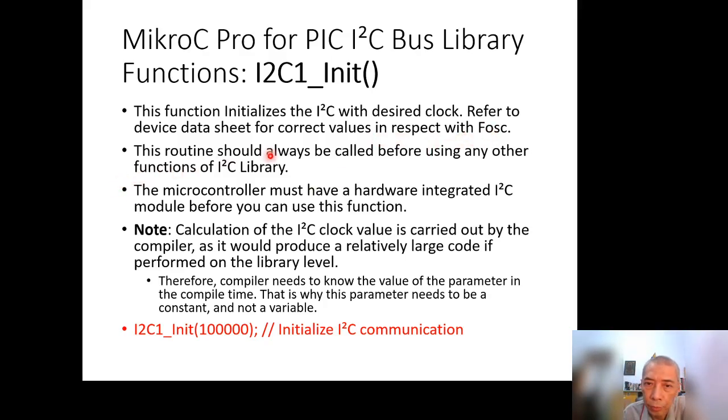This routine should always be called before using any other function of the I2C library. And the microcontroller must have a hardware integrated I2C module before you can use this function. So you have to start or initialize using this kind of function.